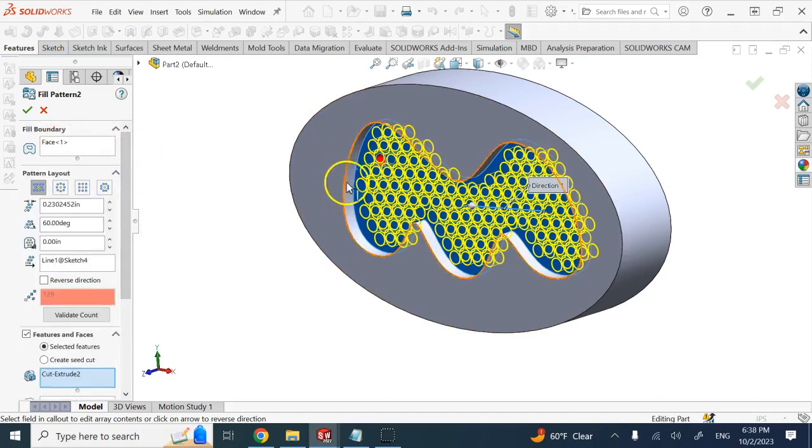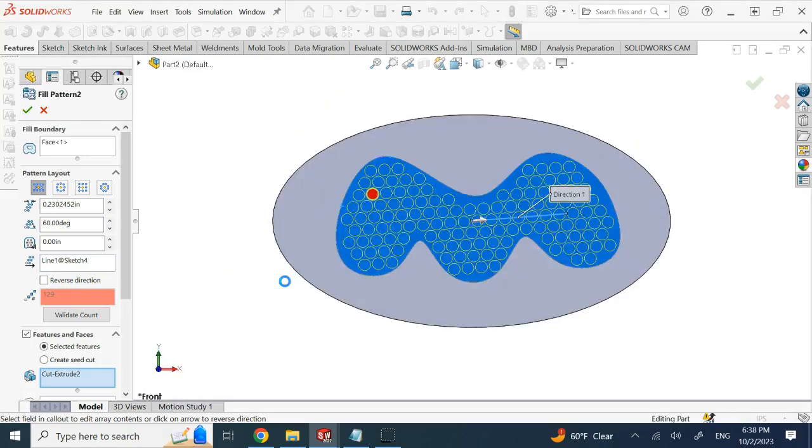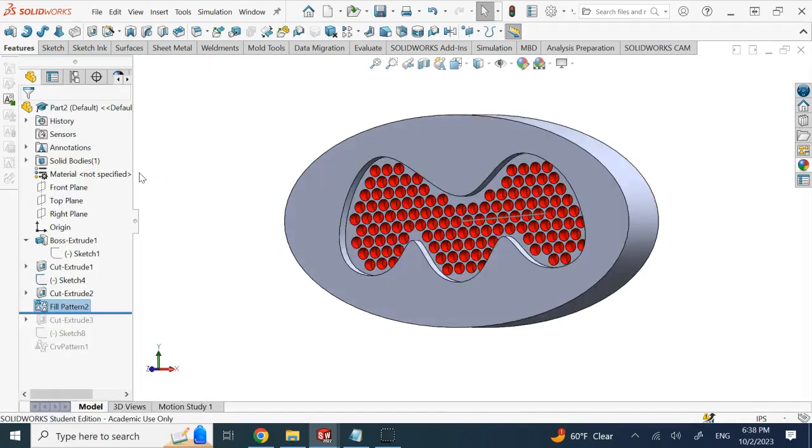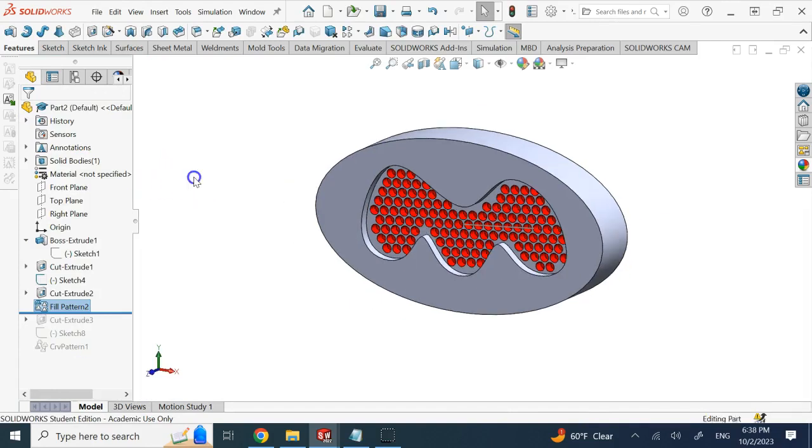I still need the back face to be the face that I put my cuts on. I still need my reference line, and I need to provide these offsets and everything. And now if you look, I get this one, right? With that pattern here, which is called perforation, right? And then there is circular, and then there is a square, and then there is this polygon. So I choose the perforation, and again, I make sure the circles are not overlaying, and look, I can get this beautiful pattern here. Okay, so this is the fill pattern.